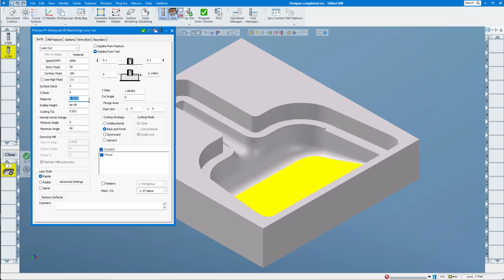Right? A step over like this will give you an incredible finish. It'll probably take, I don't know, 5 days. It'll take a long time to finish because of each line. Because we're kind of strapped for time here, what I want to do is give you an example that we can see, so I'm going to make that step over really big. Again, I pick the surface and I can just hit here and click do it.